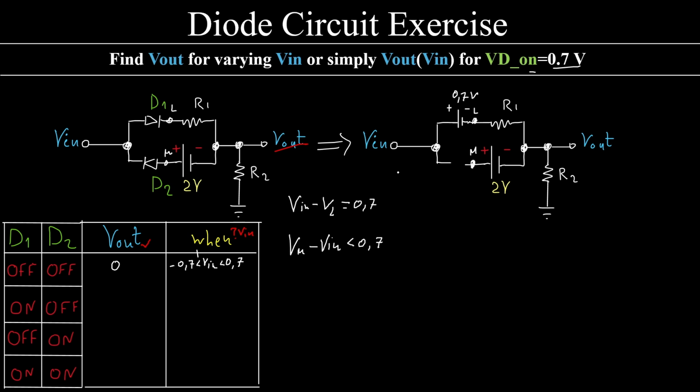How do we proceed forward now? Vm, alright, we know that Vm will be equal to the voltage over here, which will be V out. Why? Again, because this does not close a circuit between these 2 terminals. That means that Vm will be V out. Alright, I eliminated this. How about this voltage here, VL? Well, there are many ways to proceed, but this is the best.